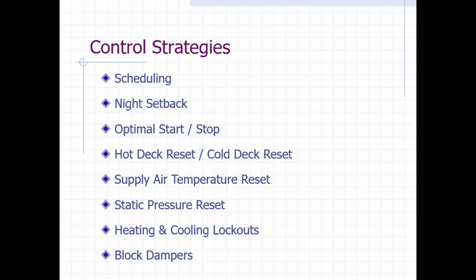I talked about lockouts and block dampers. You don't see that very often, but occasionally. And it makes sense. With air handlers, sometimes they serve many, many zones. And one zone might be a 24-hour zone, maybe a police station. And most of this air handler serves a bunch of offices, which everybody goes home at 5 o'clock. But it also serves the center that's open 24/7 and the jail, and then they've got all the people who take all the phone calls. So one air handler is serving all of that. But if we could just have a damper that would close, and then we don't have to send air to the offices because there's no one in there anyway, then we can slow down the fan, and then we could provide less air. We can save fan energy, we can save reheat energy, and we can save cooling energy. That's what a block damper does.